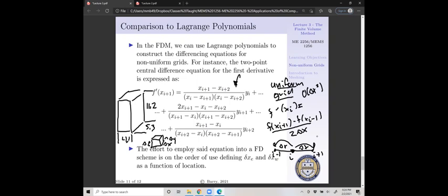So really, what's the least common denominator here? Well, we could say 0.1. So we could call that 0.1 centimeters. That'd be a relatively easy value to hit, but 0.1 centimeters might be too large of a mesh resolution because certain problems, as we mentioned within the finite volume method, at most you're going to be second order accurate.